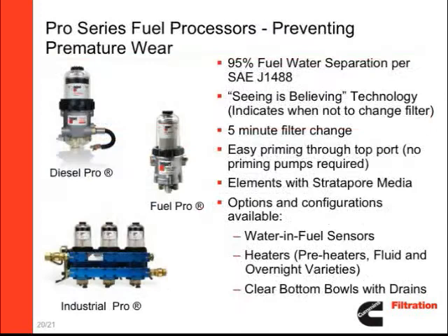Cummins Filtration offers several industry standout solutions for primary remote mount fuel filtration systems. These products provide exceptional performance. The Diesel Pro, Fuel Pro, and Industrial Pro all achieve 95% fuel-water separation per SAE J1488. They all feature Seeing Is Believing technology that indicates when not to change a filter and have easy-to-change filters for a 5-minute filter change.